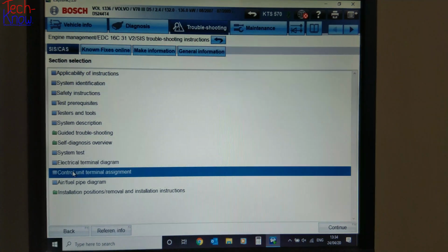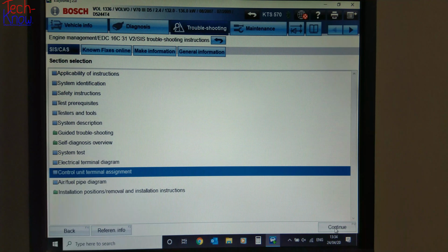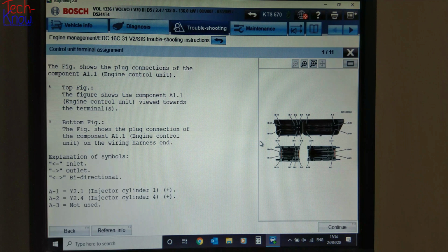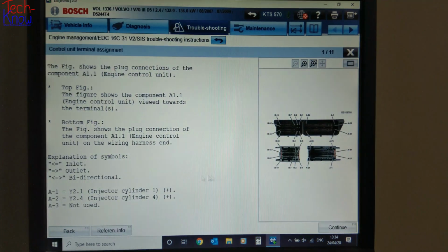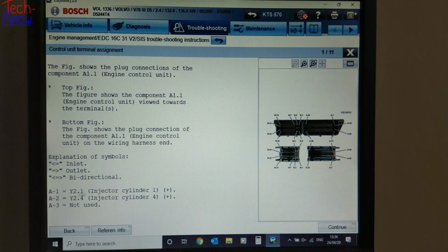Now for most vehicles, this is a photo showing us what individual components are down the left hand side and where they are on the vehicle under the bonnet. So if I just make that bigger here, you can see various components arrowed here. However, if we've got a dotted line like this one here, E6.5, compared to a solid one here, it is there, but it's hidden out of the way. It's not able to be seen from the top. So you might have to get your hand underneath there, or you might have to actually remove something to get at the component. It's warning you it's not immediately visible.